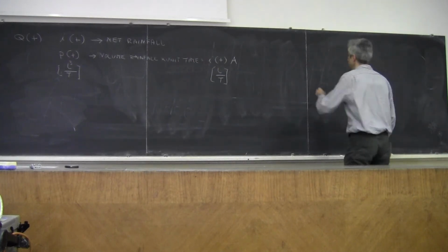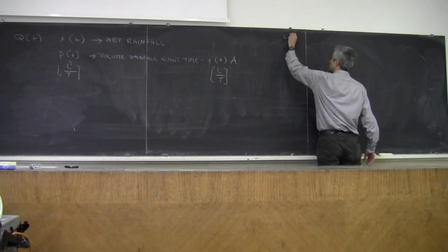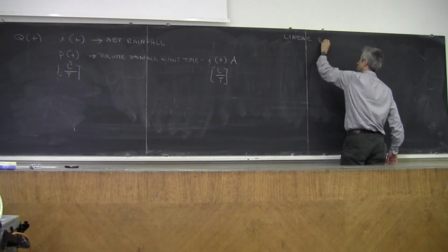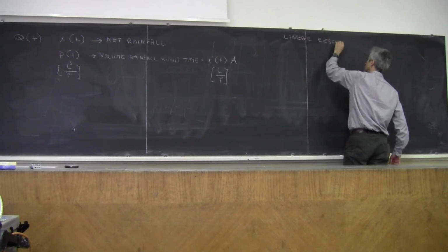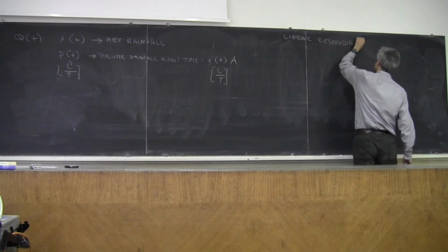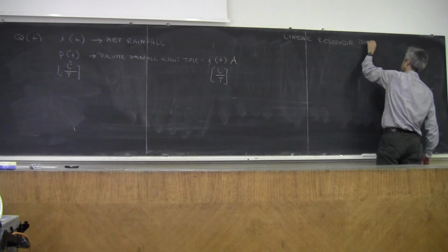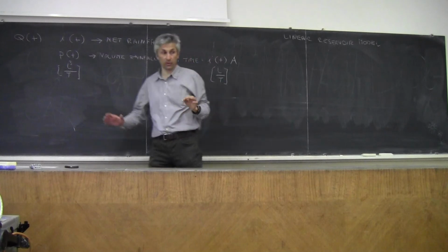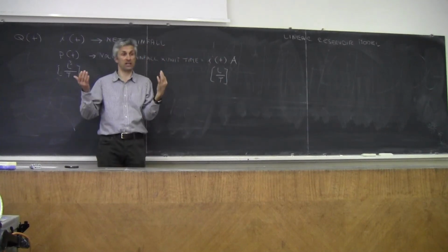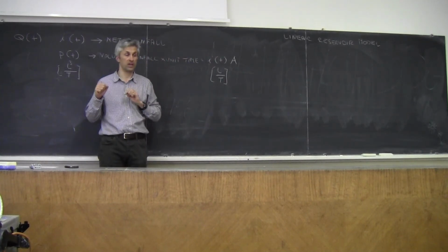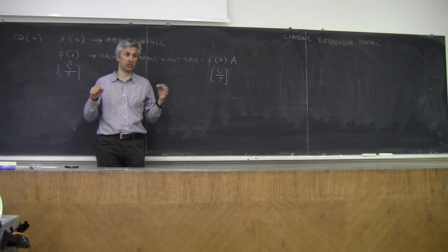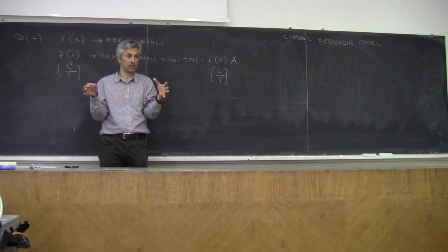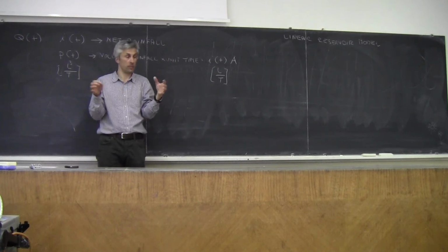The second model that I introduced is called the linear reservoir model. It is based, first of all, on the application of the mass balance equation to the catchment. And this application is done by assuming that the catchment is like a tank, like a reservoir.